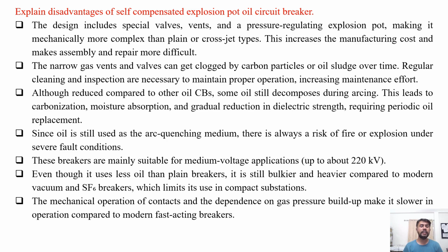These breakers are mainly suitable for medium voltage applications, that is, up to 220 kV at transmission line levels. Even though it uses less oil than plain oil circuit breakers or plain explosion pot oil circuit breakers, it is still bulkier and heavier compared to modern vacuum or SF6 type circuit breakers, which limits its use in compact substations.